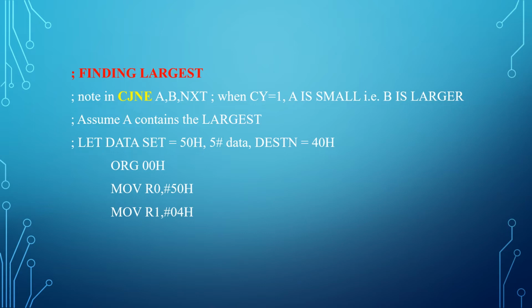Let me repeat. After comparing two values, if the value contained in A is smaller, the carry flag will be set after the CJNE instruction's execution. So we are starting the program.